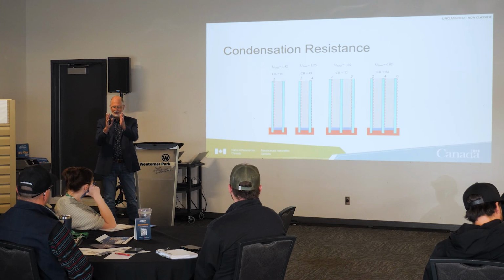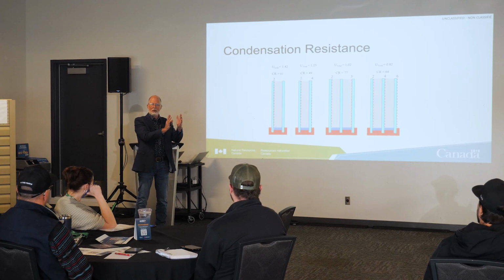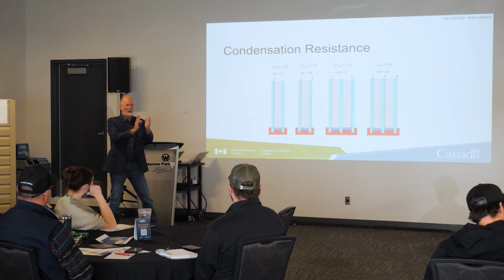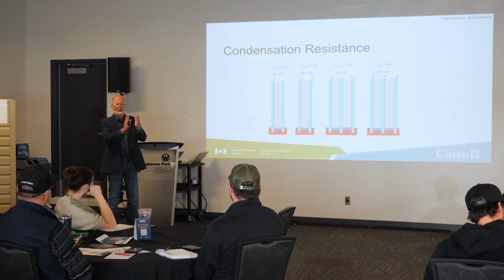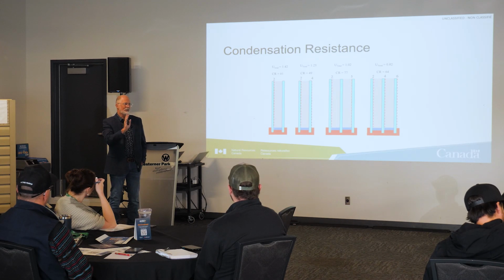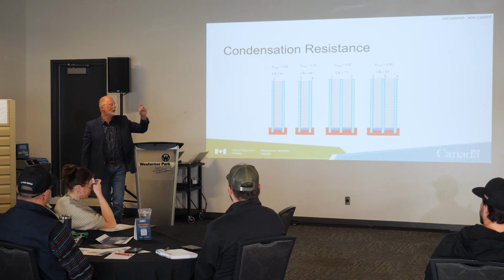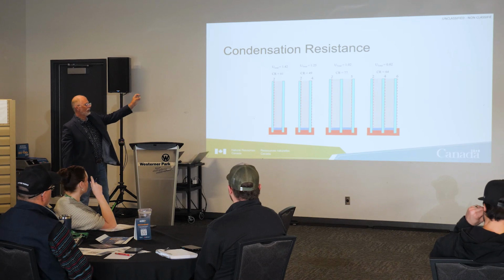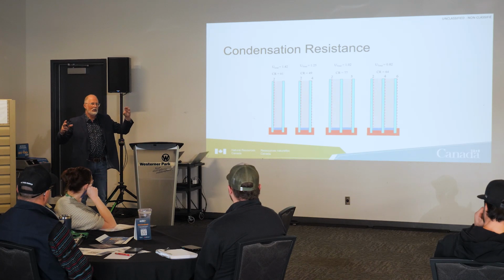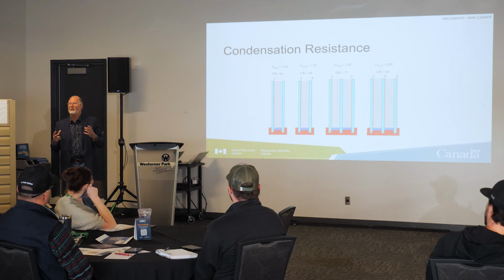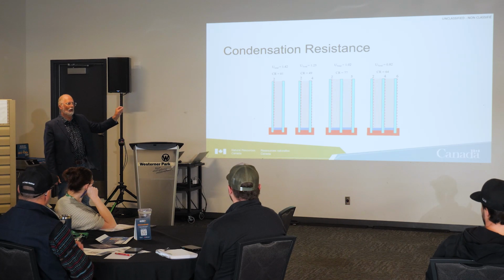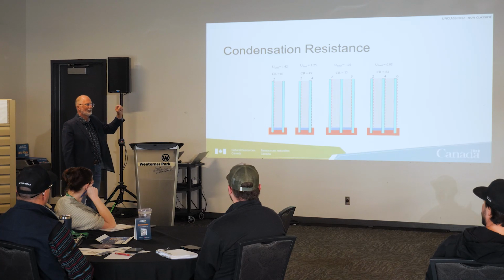So if that glass is sitting way outboard, when you put that building together, you might want to consider moving it inwards a little bit so that you're getting more air movement towards that glass surface. This is just one of your toolbox, right? You've got ventilation, you've got air movement, you've got condensation resistance, you've got U value, solar heat gain. You need to put those all together. We talk about a building as a system. Here's a classic example of the windows being so critical in this system.